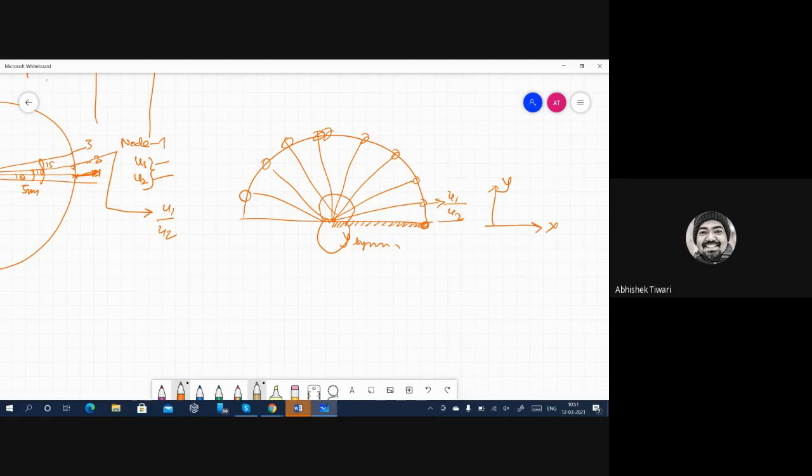Because if you take the object, then the boundary condition will be applied on the object somewhere. If you make it dependent, mesh it in the part, then apply, the boundary condition will be applied exactly on the node. Okay. How will you find out on which node you have to apply? You can have different ways.